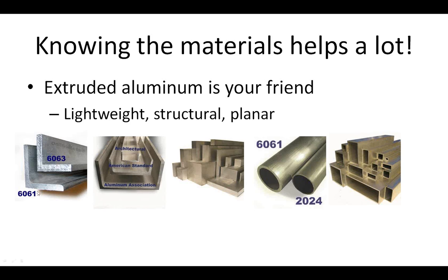The secret numbers here, 6061 is a specific kind or formula of aluminum. It's kind of the standard, and that's probably 99% of what you're going to use, okay? And you can see this is angle aluminum. See, it's got a little radius down here, so it's a little stronger. That's called structural aluminum. The 6063, that material is a little softer, and it's oftentimes used more in decorative or architectural uses. And you see it has a square corner on the inside.